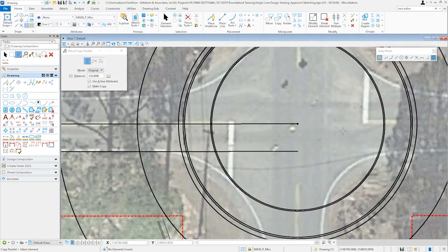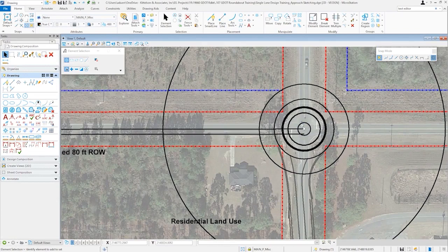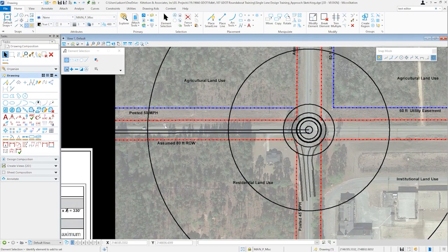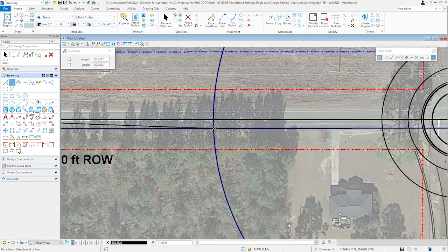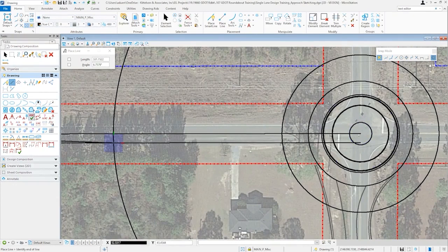If you recall, we would like to have offset left geometry. So as a ballpark, I usually start by offsetting 10 to 20 feet. In this case, I'll choose something in the middle, and I'll put in a radius of 15 feet, and we want to line up tangent to that to develop our offset left approach alignment. So if I connect these points, we'll start at the beginning, the 35 mile per hour line, and then we'll come in on our offset left approach.